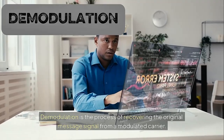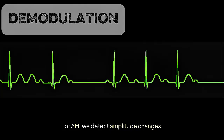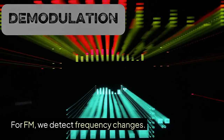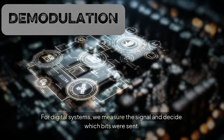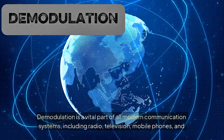Conclusion. Demodulation is the process of recovering the original message signal from a modulated carrier. For AM, we detect amplitude changes. For FM, we detect frequency changes. For PM, we detect phase changes. For digital systems, we measure the signal and decide which bits were sent.